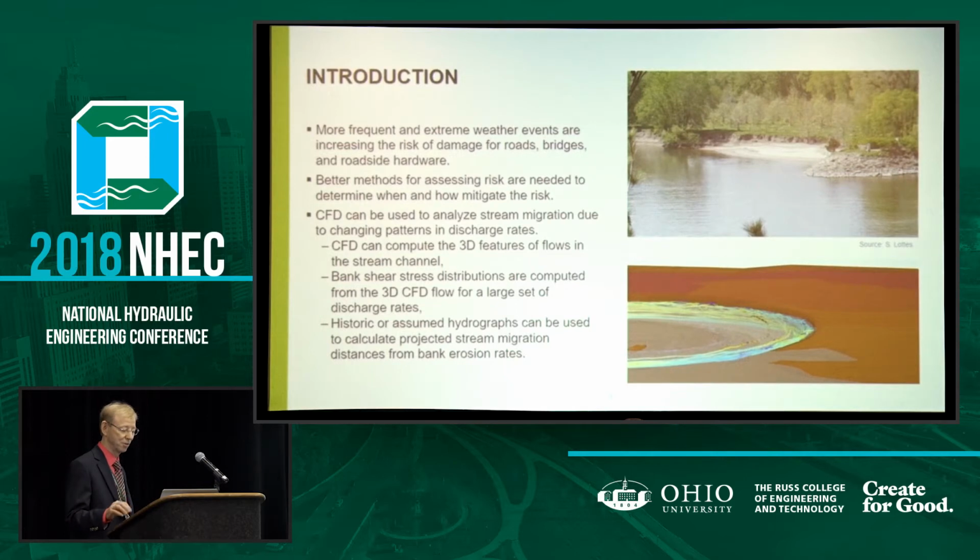It's a series of horseshoe bends that's very active. And in the lower right here, you can see streamlines going through the bend and how they're all twisted. That shows the secondary flows there. So what we're after there is the shear stresses on those banks so that we can get a rate function for the removal of material.